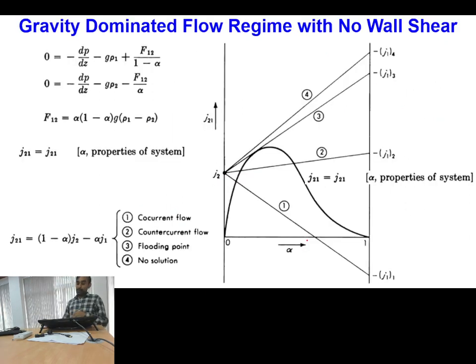Now we will try to see the applications of this drift flux approach, how it can help in determining different characteristics of the flow. Majorly you have to remember that this approach will be applicable where there is a strong relative motion between the phases, and this relative motion is not controlled by the inlet flow rates of the fluids. So there this approach is applicable.